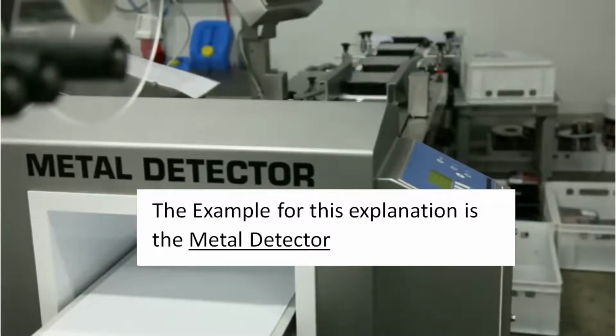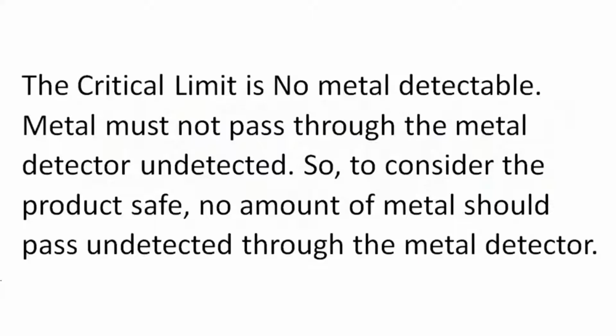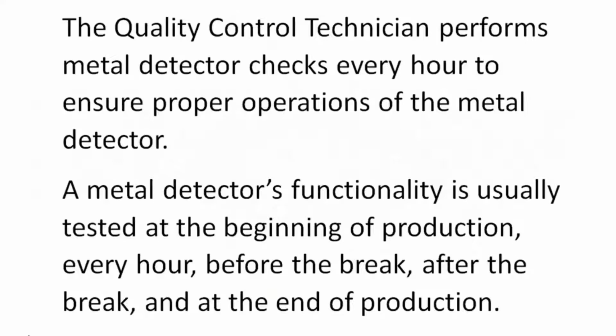The example for this explanation is the metal detector. Critical limits. The critical limit is no metal detectable. Metal must not pass through the metal detector undetected. So to consider the product safe, no amount of metal should pass undetected through the metal detector. Monitoring. The quality control technician performs metal detector checks every hour to ensure proper operations of the metal detector. A metal detector's functionality is usually tested at the beginning of production, every hour, before the break, after the break, and at the end of production.